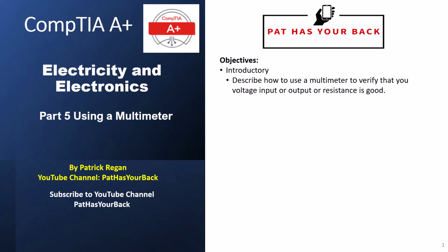With computers, you can use a multimeter to test connectivity of a wire, test connectivity of an ESD strap, and test the voltage output of the wall outlet, batteries, and power supply. While this is not as cool as some of the other videos, this little skill can help you troubleshoot computer problems that are related to power problems and to test wire connectivity. This video will also help reinforce how conductors and insulators relate to voltage and resistance.